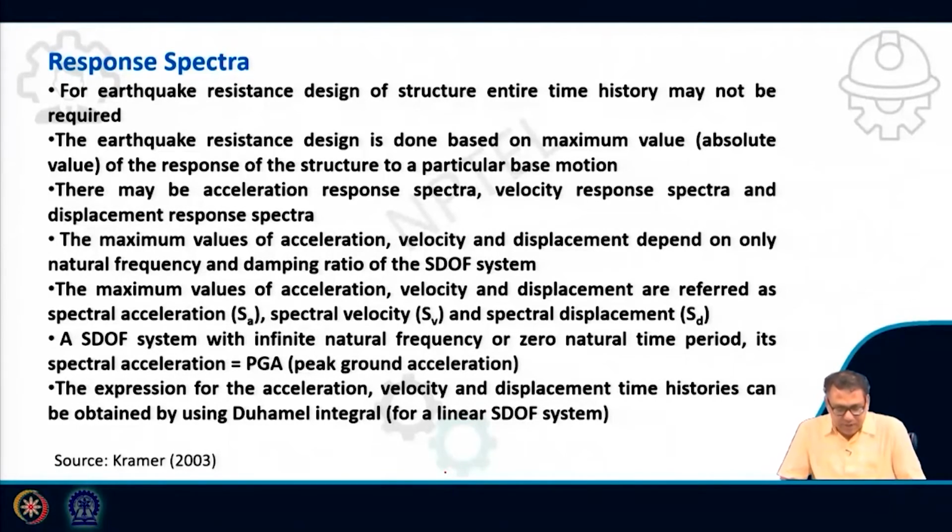The maximum values of acceleration, velocity, and displacement are referred to as spectral acceleration, spectral velocity, and spectral displacement. I have shown how you get the maximum value for displacement. In a similar way, you can get it for velocity and for acceleration also.